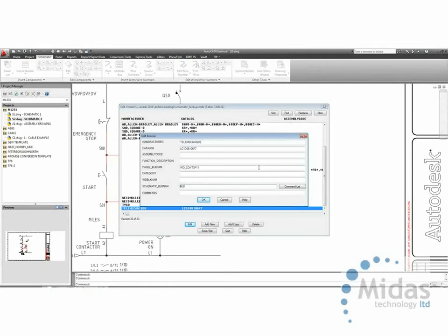It could, however, have just had MS1. It doesn't need the V or the H at the front. It will automatically pick up whether it's V or H depending on the drawing properties. So this is how it recognised what block to place.